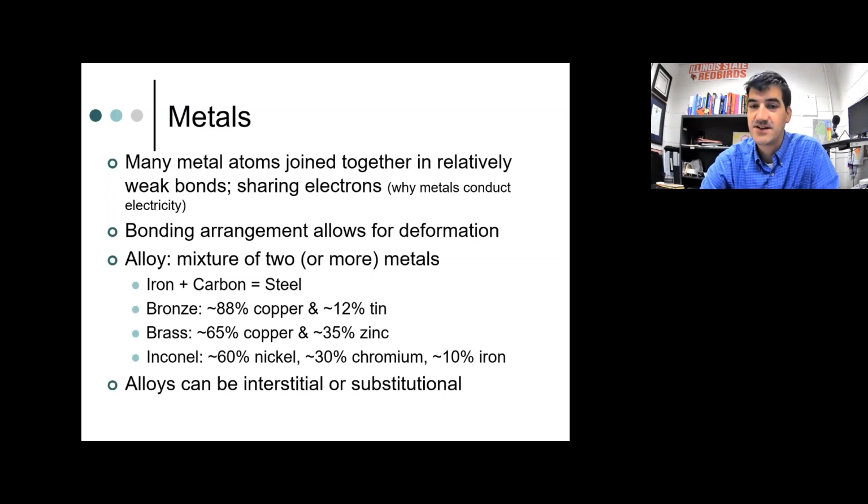Inconel, by the way, is a very corrosion resistant and also very strong material. It's expensive, but it's what's used in really high temperature, high corrosion environments. In my industry experience, we used Inconel for steam piping and steam generator tubes, things that would be exposed to really high temperatures and high potential for corrosion where you really didn't want them to corrode.